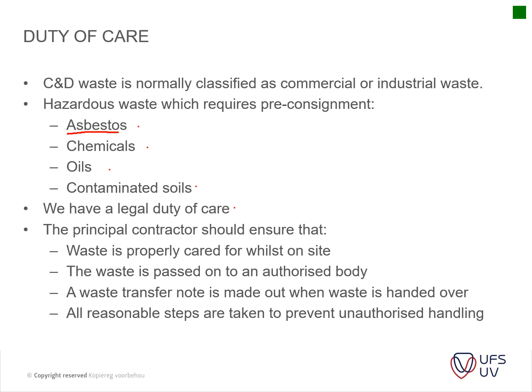Okay, then the principal contractor should ensure that waste is properly cared for whilst on site. Waste is passed on to an authorized body. A waste transfer note is to be made out when waste is handed over. All reasonable steps are taken to prevent unauthorized handling.